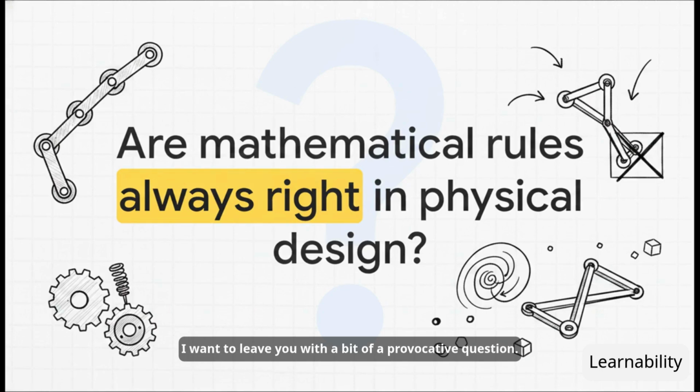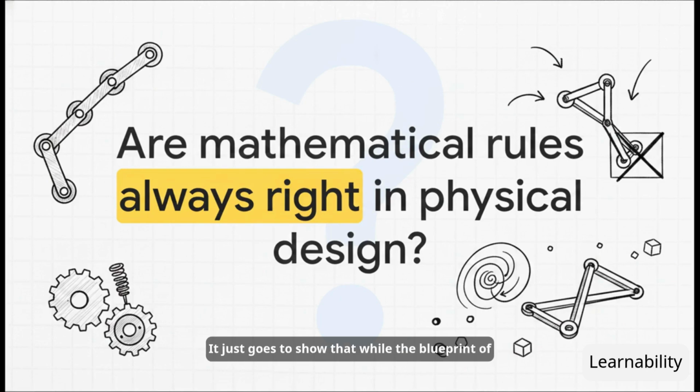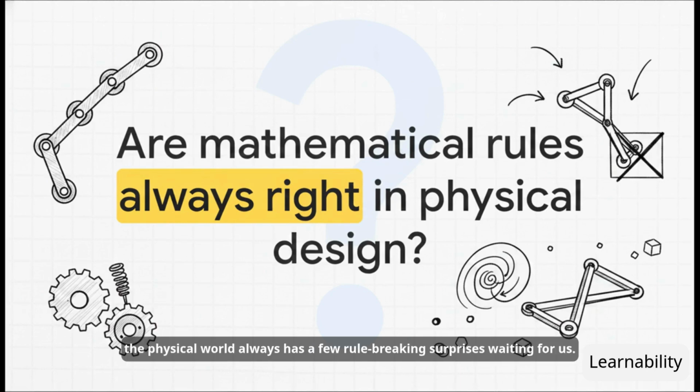But I want to leave you with a bit of a provocative question. Are these strict mathematical rules, like the Kutzbach criterion we looked at earlier, always 100% right? Well, spatial anomalies, like the famous Bennett linkage, prove that sometimes Kutzbach calculates that you have a rigid, locked structure, but because of some very special, twisted 3D geometry, the thing actually moves anyway. It just goes to show that while the blueprint of motion gives us amazing predictive power, the physical world always has a few rule-breaking surprises waiting for us. Really makes you want to dive into advanced spatial kinematics next, doesn't it?